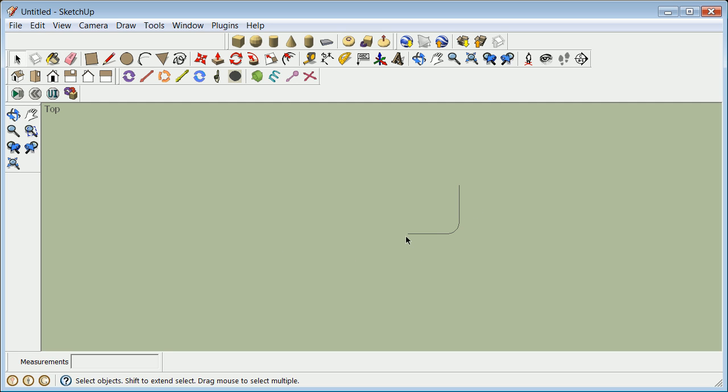That's all well and good, and it started at 0, 0, so we're going to move this out now. I grab my tool, I go from here to here, and I go back out. All right, so that is the alignment to which we want to bring our typical cross section. Once again, I'm going to turn on View, Axes. I'm going to draft, because you really want to at least think that your typical section is right there at the 0, 0. So I'm going to draft right now, just arbitrarily, a typical section starting there.